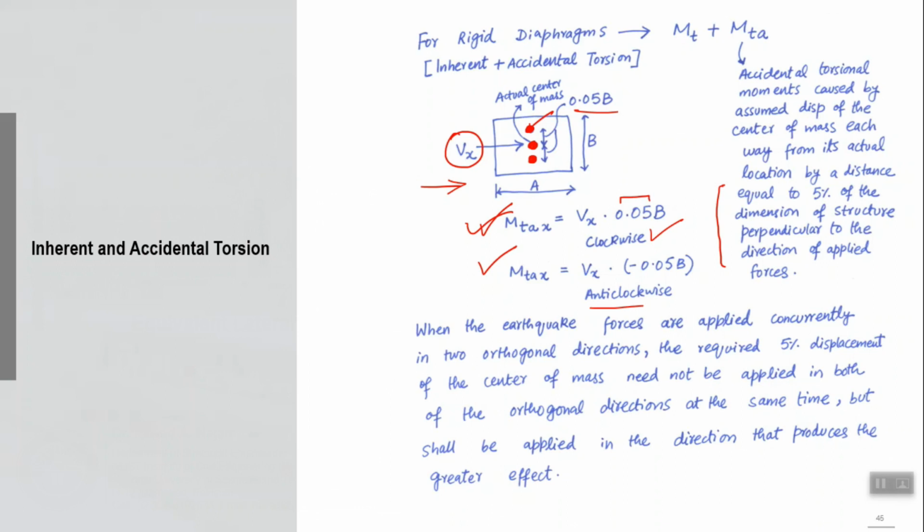So generally how we handle this situation is that if we have one load case in which earthquake is included, we convert it into 3 load cases. In one combination we use this particular load case, in another combination we use this one, and in the other one we use this one. So we divide our load combinations into multiple combinations. Actually we multiply them into different further combinations.